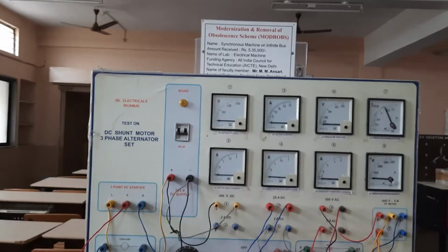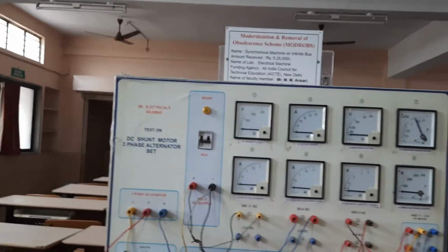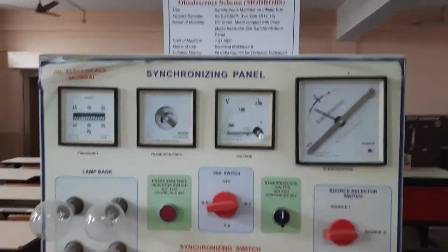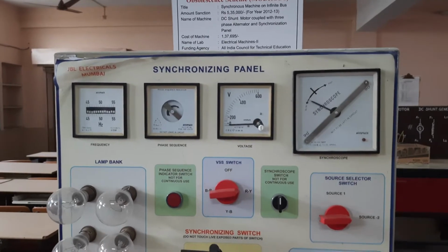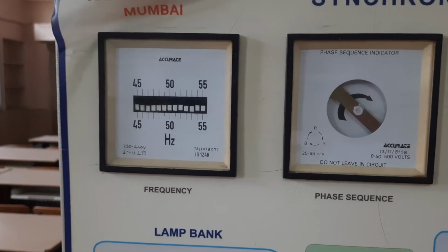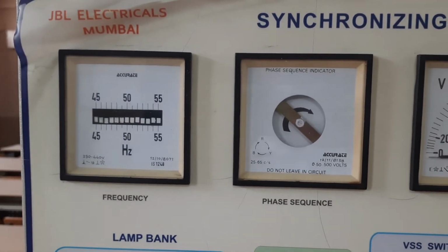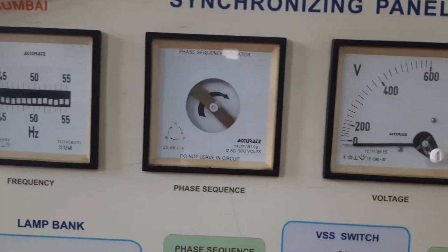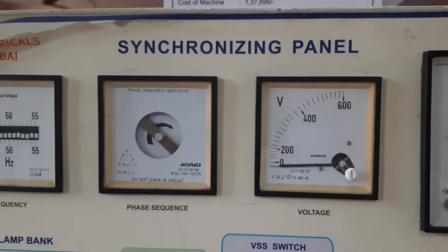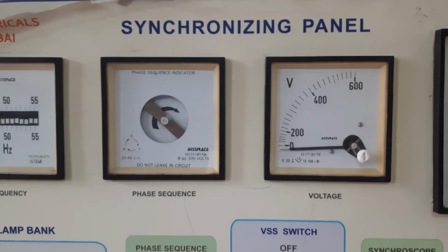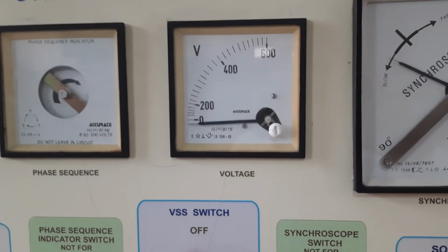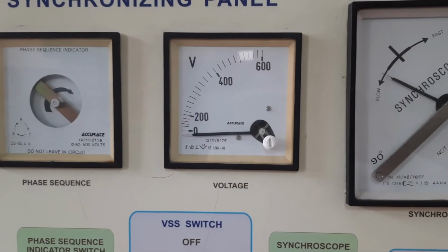This is the 3-phase alternator, meaning a DC shunt motor coupled with the 3-phase alternator. The second part of this practical setup is the synchronization panel. This synchronization panel consists of a frequency meter, which measures the frequency of the incoming generator as well as the grid. Second is the phase sequence, which indicates the phase sequence of the infinite bus and of the incoming generator. Then the voltage measurement of the infinite bus as well as the voltage of the 3-phase alternator